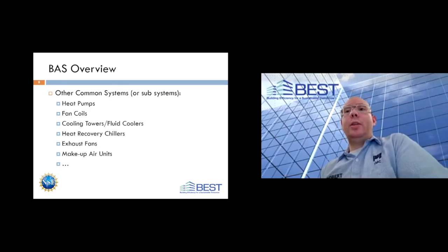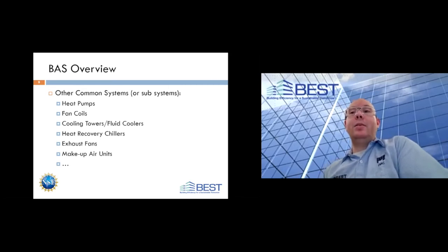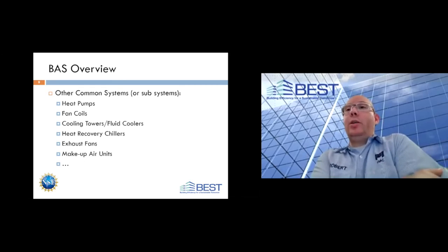Also, boilers aren't the only way we can make hot water. Heat recovery chillers are, again, one of those items becoming progressively more and more popular within various parts of the world. Using what would typically be considered waste heat from chilled water production to heat up water for the building. This can be heating water, this can be hot water for sinks and dishwashing and all those kinds of things.